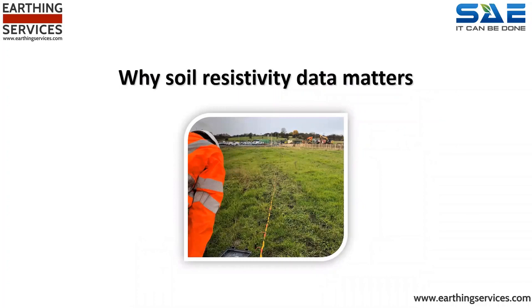Why soil resistivity data matters. Before an electrical earthing system can be installed, a few other activities should first be undertaken. Historically, installation companies may have offered to drive a single earth rod and take a range of readings from it at various depths as it is driven into the ground.